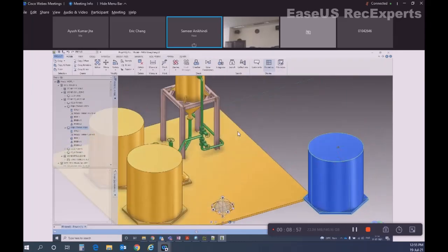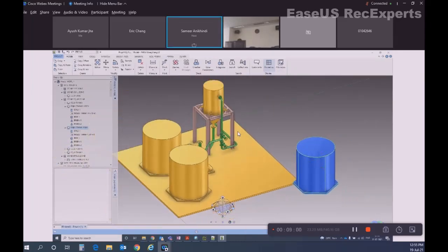So M enter is move. Let's see, I move it in a more complex manner. I want to align the easting of both of these equipment. How will I do it? Right. So M enter again. Base point, I want to pick the origin, so I will pick the item snap. Now I want to match the easting. I just want to match the easting. I don't want to change anything else. So I will lock the northing, tab 0, elevation, tab, enter.